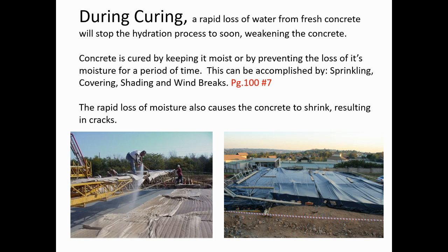When you're curing the concrete, the water is our secret ingredient to activating the chemical reaction. If you don't have the water, you won't have a chemical reaction to cure the concrete and make it hard. So if you're pouring and placing concrete on a hot, sunny day, you need to keep the surface nice and moist. You can see in the picture below, they spread out burlap, and they have somebody with a hose, or sometimes a water sprinkler. They're just keeping that wet for a couple days to make sure that it cures properly.